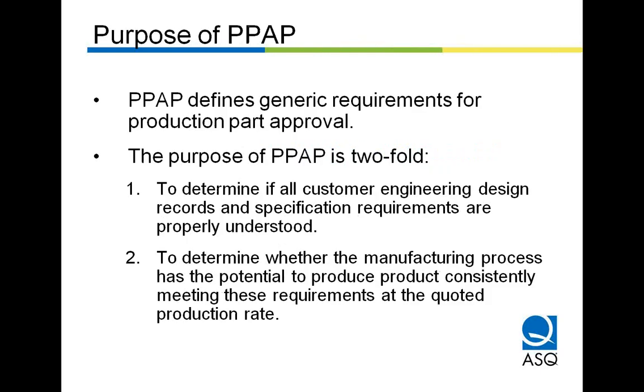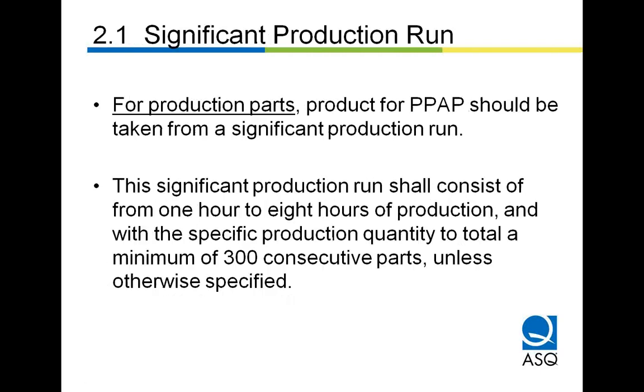The purpose of the PPAP is twofold: demonstrate that the design requirements, those specifications, are fully and properly understood, and secondly, that the manufacturing process has the potential, at least, to produce the product consistently meeting these requirements at the production rate. I sometimes refer to that as being a robust and capable process.